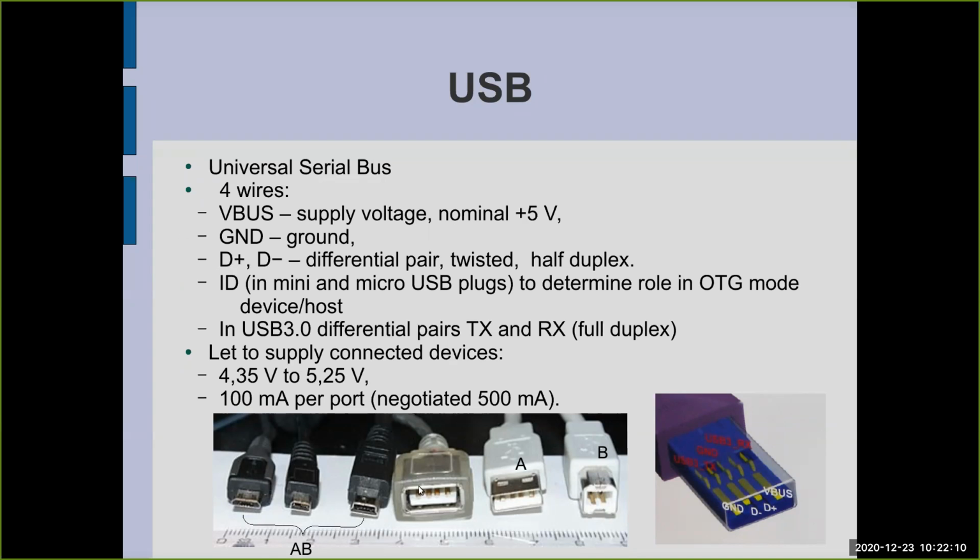And look at this plug, you can see that it is similar to Serial ATA. The data lines or pins are shorter than the ground and power supply lines. So if you connect your device, first the ground and voltage are in contact, and after some time the data lines are connected.